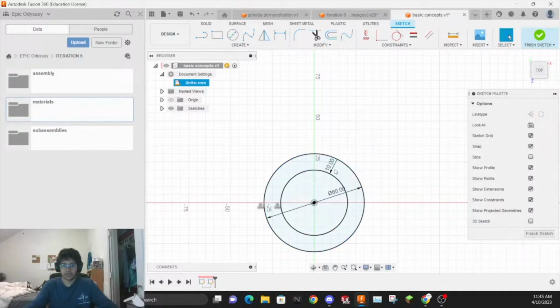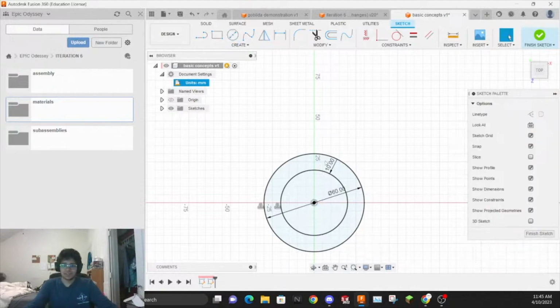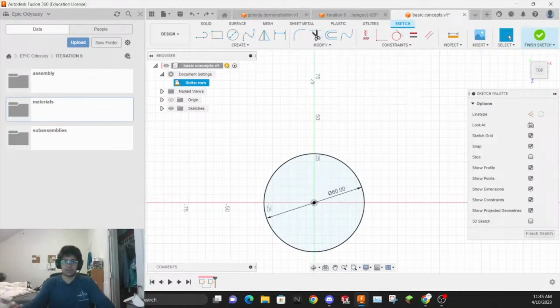Now you should have a 50 centimeter hole. Or no, not 10, because then you'll get 40 centimeters, or 40 millimeters, yeah. So you kind of have to think. You have to use math, right? I know it sucks, but you're gonna have to use math to figure out offsets, because your offset's gonna apply to the entire shape. So you're essentially doubling the amount of offset to affect a new shape. Like you saw before, my offset was only 10 millimeters, but the entire inner diameter changed by 20 millimeters, because you have 10 millimeters on this side and 10 millimeters on this side that you're offsetting.